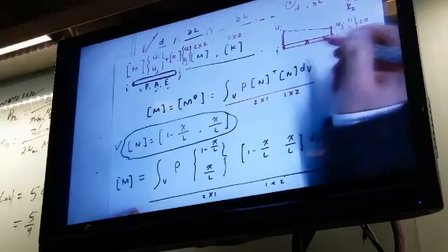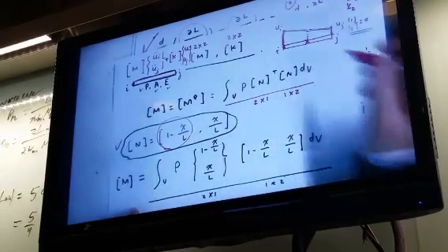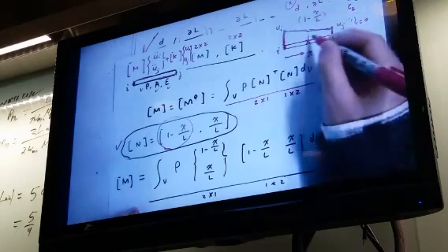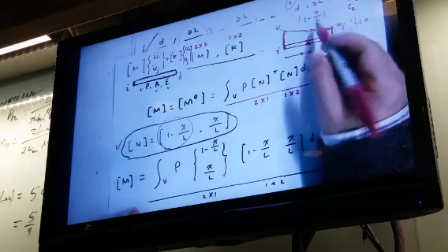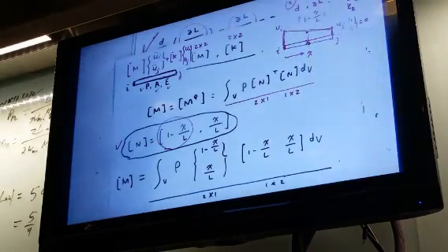And what is the displacement here? This function will tell you what it is, where this is the x direction: 1 minus x over L. So you tell me what the value of x is, and I will use this function to tell you what the displacement is here. This is called interpolation. You have the displacement at the two ends. I want to figure out the displacement at one point in between. I do not have to calculate it, I just want to do the interpolation using a defined function. You can define a nonlinear function, a high-order polynomial, to do the interpolation, but this is the simplest one. You can just use linear interpolation, so-called first-order interpolation.